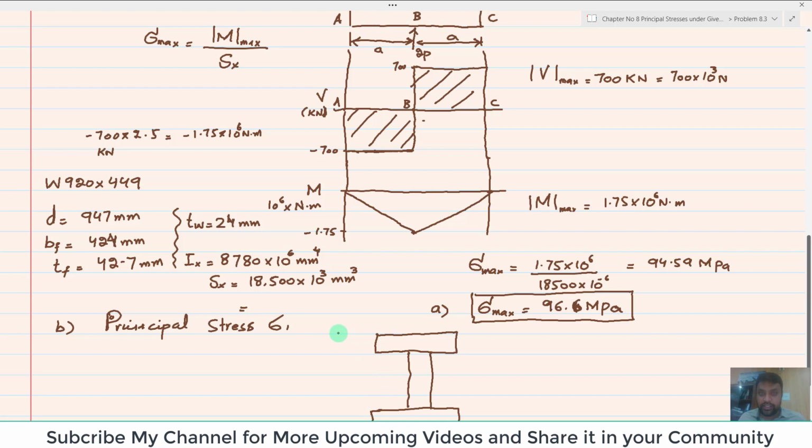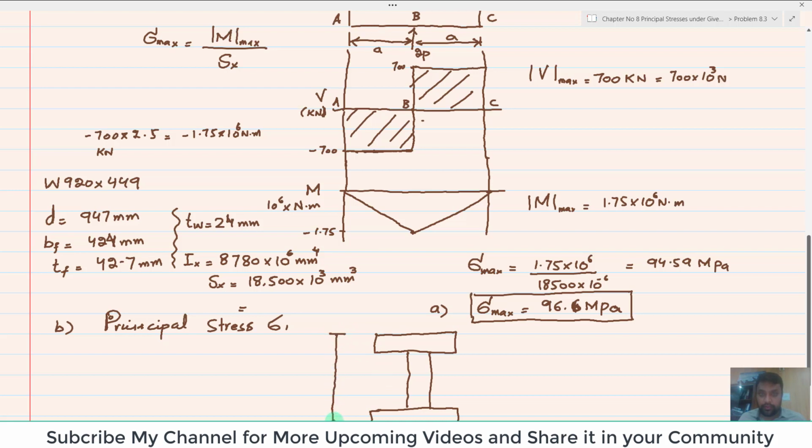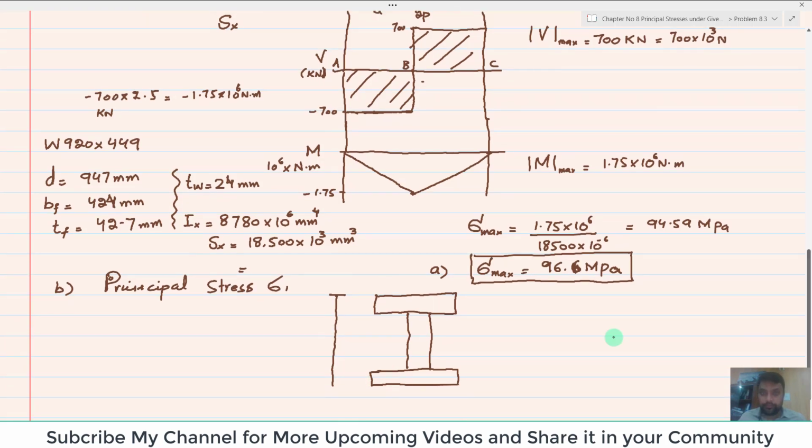So total height is D. If you divide D by 2, that will give you the centroidal axis. So this distance will be C, and this C will be equal to D divided by 2. When you put the value of D, 947 divided by 2 will give you 473.5 millimeter. Clear? Now this is the distance from the neutral axis to the topmost surface.